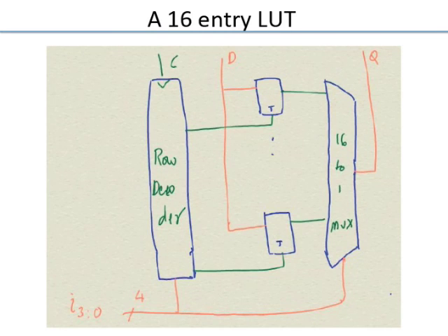So now let's just look at this complete lookup table. For your project, you have a 16 entry lookup table. So you have some memory elements. Let us say for now you use the latch. I put the T out here because you don't want to use a flop. A latch is good enough for something like this, and you have less area. And the latch has, I label this T, which is where the clock input comes. So you have 16 such entries.